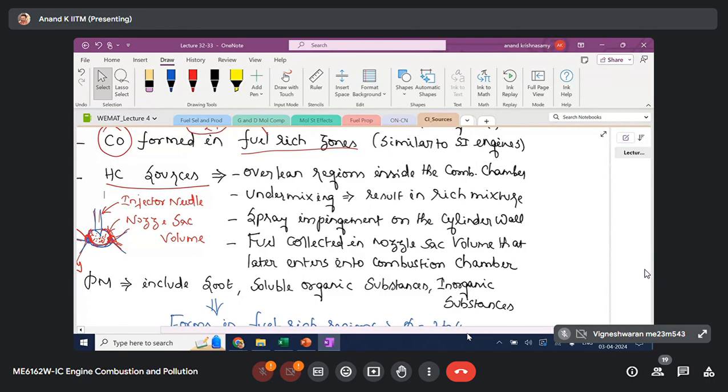So you know there is an ignitable range of phi. There is a phi that is ignitable, and this is also called the flammable range of phi. There is an upper limit and there is a lower limit. When I say lower limit, it is on the lean side. When I say upper limit, it is on the rich side.